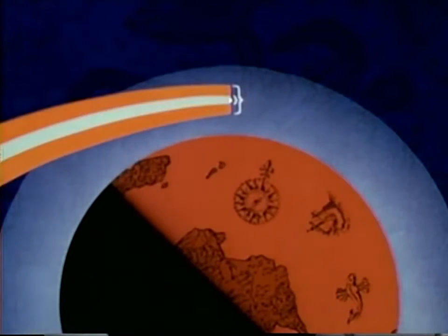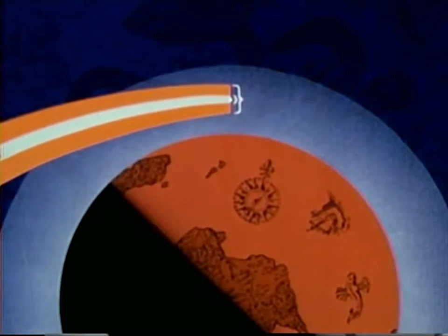However, with the limitations of hardware and trajectory design over translunar distances and velocities, it is impossible to control the trajectory to guarantee an approach closer than this to the nominal vacuum perigee altitude. Since this is directly related to the entry corridor, it can be seen that if atmospheric drag alone is used as a controlling factor, it is impossible to guarantee a safe entry.